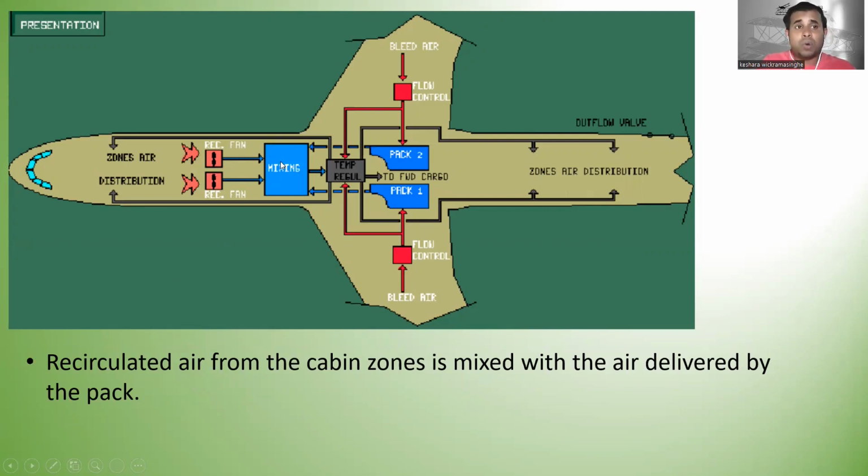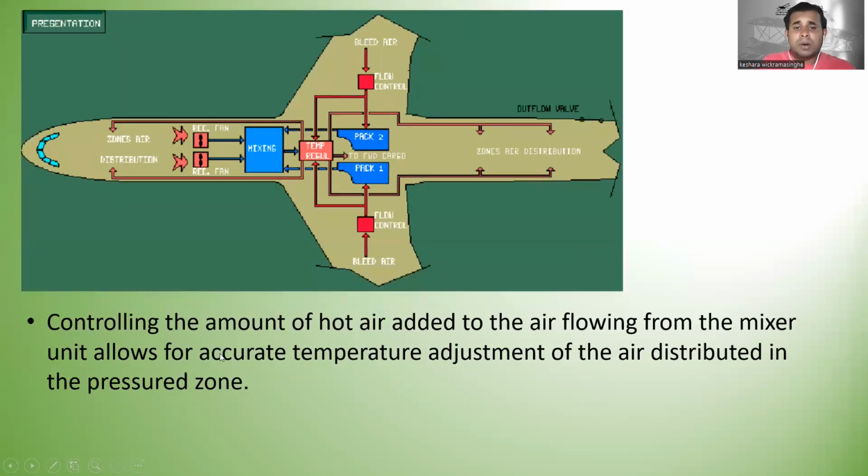So then it's mixed over there, right? Okay. So controlling the amount of hot air added to the air flowing from the mixer unit allows for accurate temperature adjustment of the air distributed in the pressurized zones.